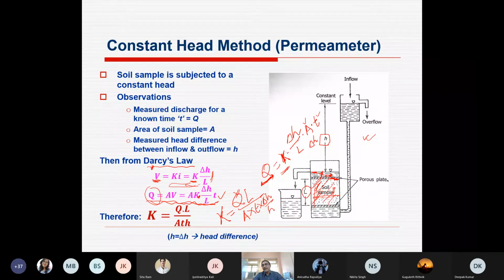So this is the simple laboratory arrangement, but we need to take care during sample collection so that soil is not disturbed from its original condition in the field. How do we collect these samples? By using core samples and augers, that is, one instrument, a core sampler auger arrangement, so that at the desired depth in the soil we collect the sample.